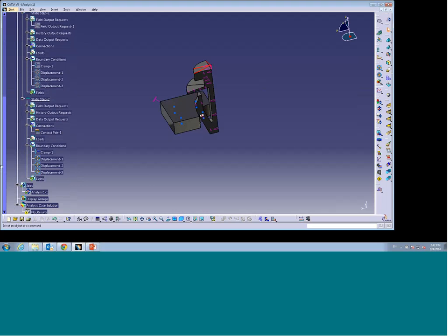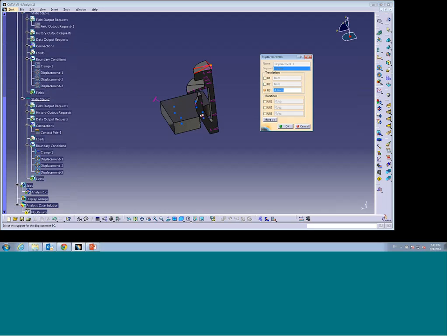And lastly, I also need to change the boundary condition. So displacement 3 was controlling the enforced displacement in vertical direction. Gonna double click. So you see initially it only went up to 1.8 millimeters. The next step is actually another about 1 millimeter. Let me find the value real quick. And if I'm not mistaken, hold on a second. Yeah, that was 6.25 millimeters.